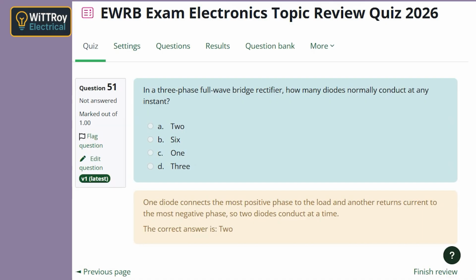Now give me the single-phase ripple figures. Half wave is the same as supply frequency, so 50 Hz. Full wave is twice supply frequency, so 100 Hz. Good. What about PIV? It is the maximum reverse voltage the diode must withstand while it is blocking. The diode rating must be above the circuit PIV, with a margin.